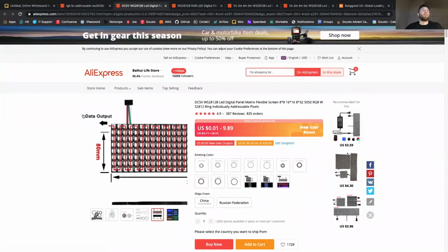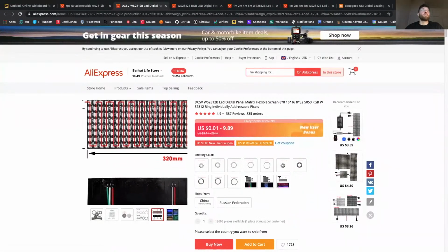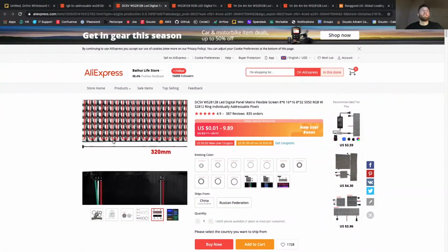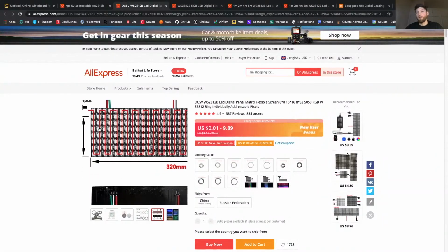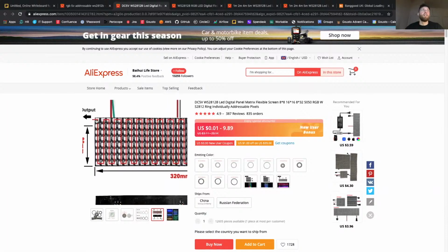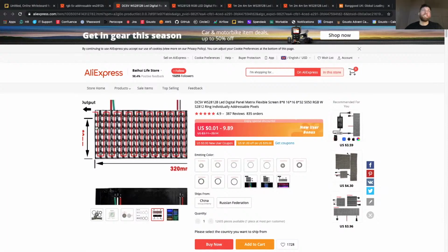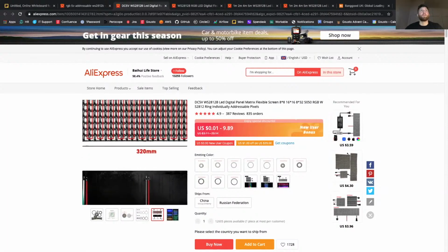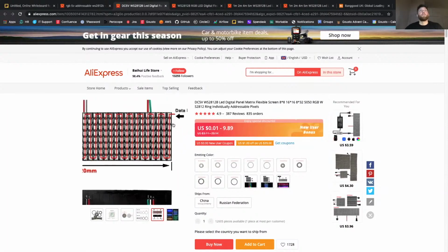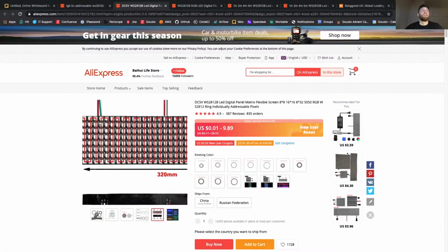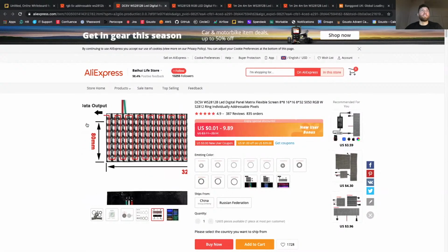And look, there you've even got an address sequence diagram showing how the addresses snake through. We're going to get more onto exactly how the addresses work later. But if you start thinking about it, this is the first LED and this is the second and this is the third, and it snakes back and forth in that type of sequence. So each LED has an address.